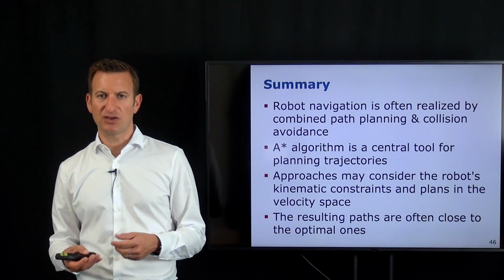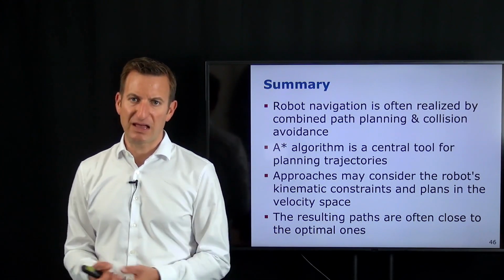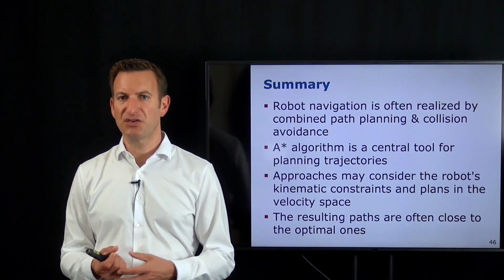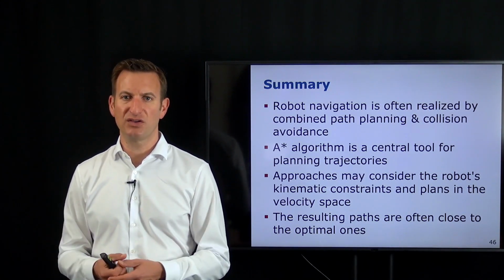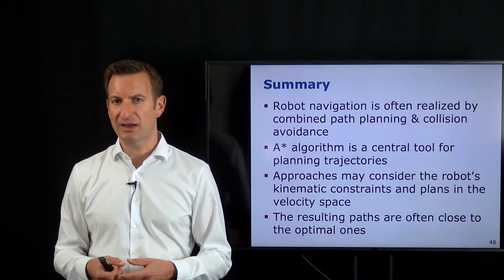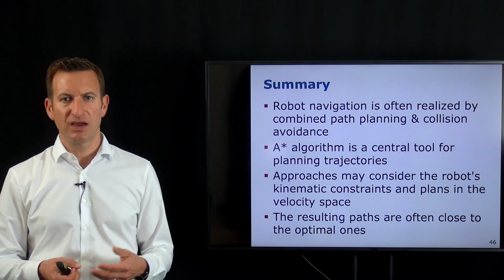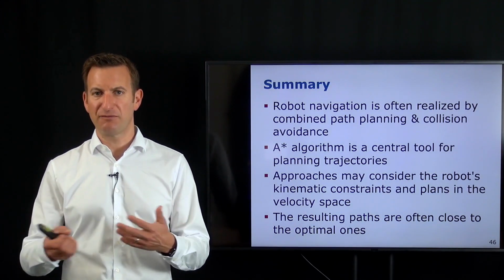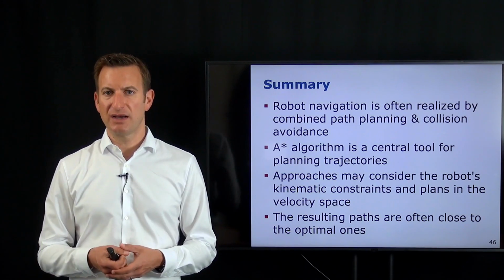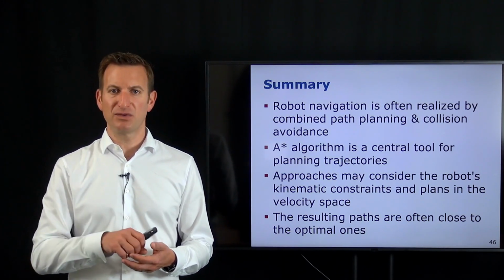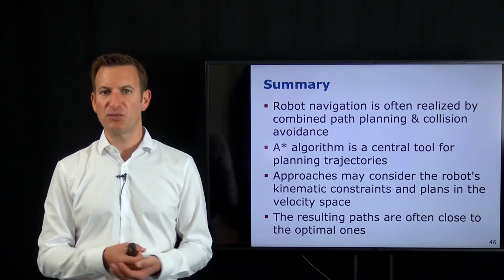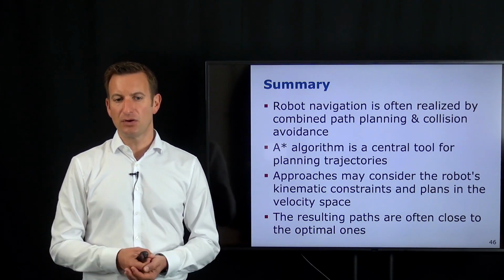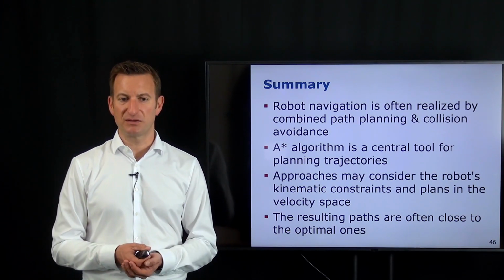And we can also extend this, this was kind of the last part of this lecture here, if we go to higher dimensional state spaces, taking additional things into account like velocities, we can incorporate kinematic constraints like braking and acceleration behaviors, and we actually generate better trajectories that are not aligned to this 45-degree grid structure, where I can only go in 45-degree orientations, but actually generate smooth trajectories for mobile systems, also navigating elegantly through confined spaces, which is very convenient.